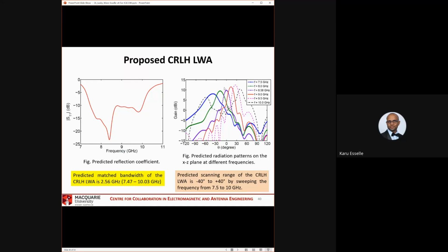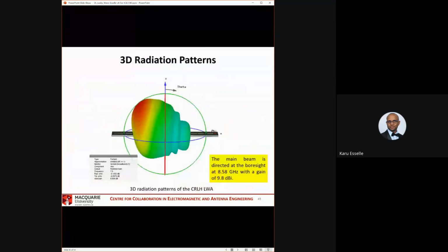Remember in one of the leaky wave antennas we looked at before, when you try to go past the broadside, the directivity and gain drop a lot. It doesn't really work. But properly designed composite right-left antennas can steer across broadside to the other side continuously.